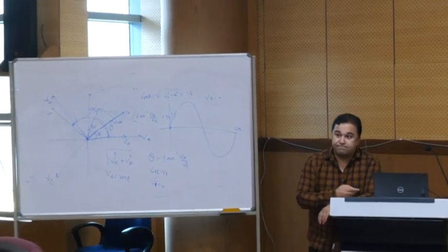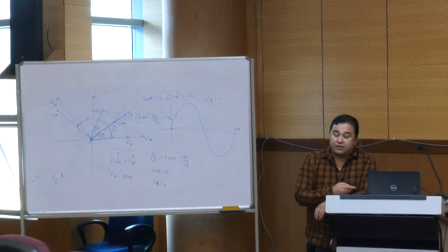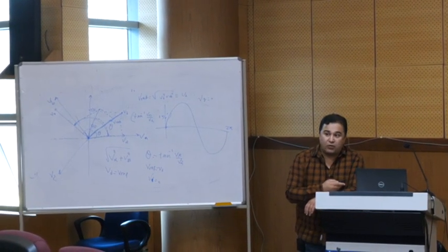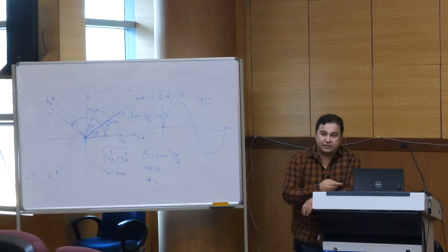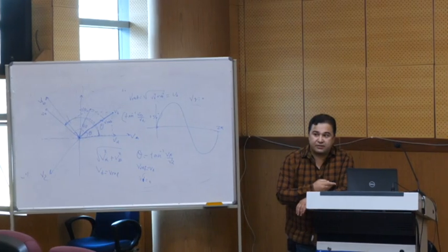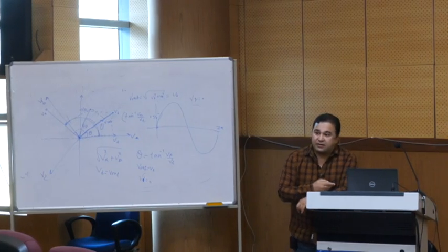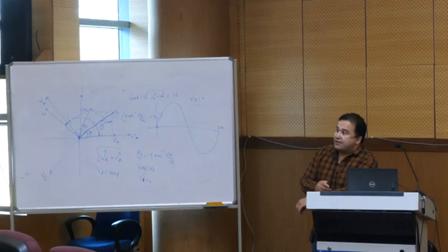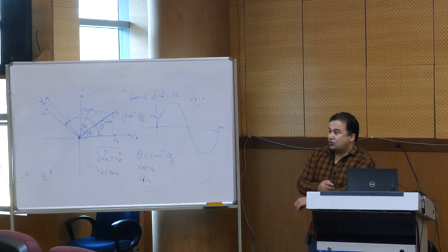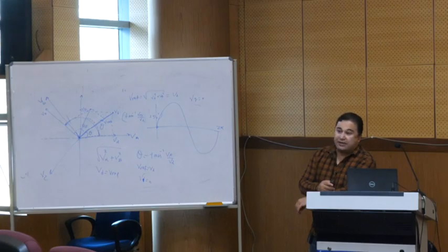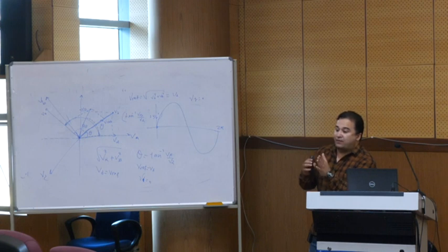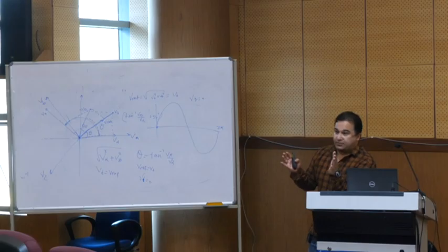Can we get a similar situation using Clarke transformation between V alpha and V beta? When you talk about the Clarke transformation, there is one benefit: the alpha axis and the beta axis are always decoupled.